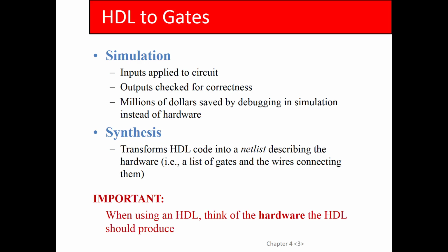For simulation, there's a tool that came out a few years ago called Icarus Verilog, which is actually the tool I used to generate that waveform that was on the test. And there's another one now called Verilator that's even more popular than Icarus Verilog. Verilator is kind of cool because it's a different methodology. Instead of simulating, it converts your code into a simulator. You actually compile your Verilog into an executable file and run it, and then it behaves like the simulator would. So it doesn't have a separate simulation engine, which is a subtlety. But anyway, most open source people use Verilator now.